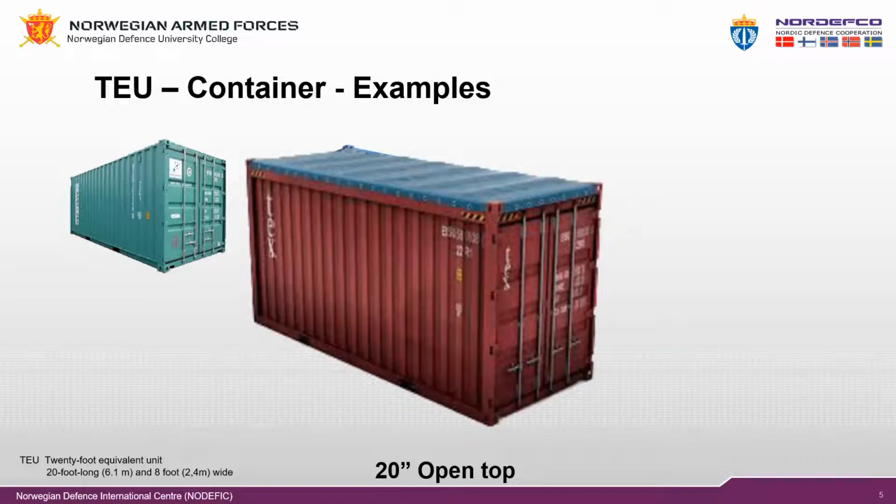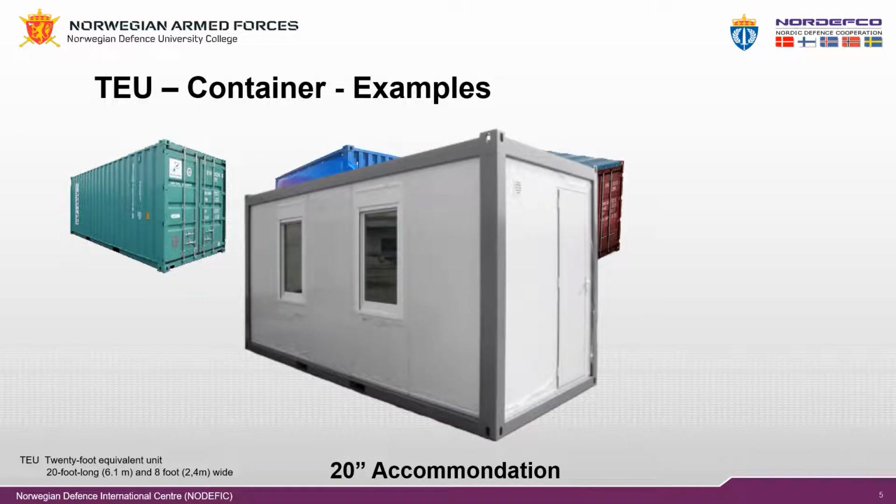The following must be taken into consideration when planning the stuffing, the loading, of a container. Floor loading. Load spreaders should be used to distribute the weight of heavy loads with a small footprint across a larger area. Even distribution. The load should be planned so that the weight is evenly distributed throughout the length and width of the container, with the high density cargo stowed at the bottom and the low density cargo above. This keeps the center of gravity at the lowest possible point.